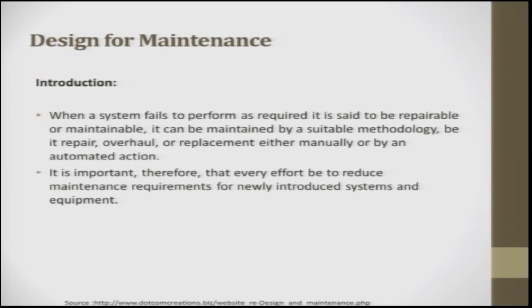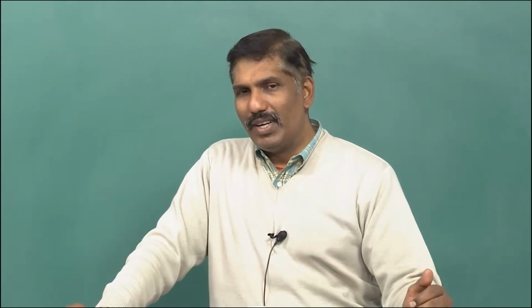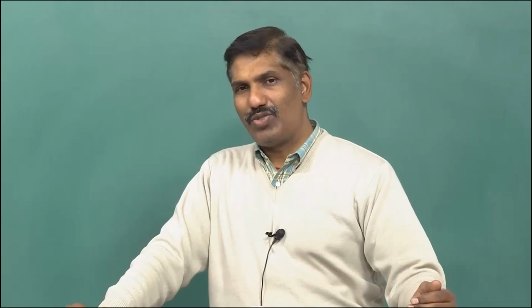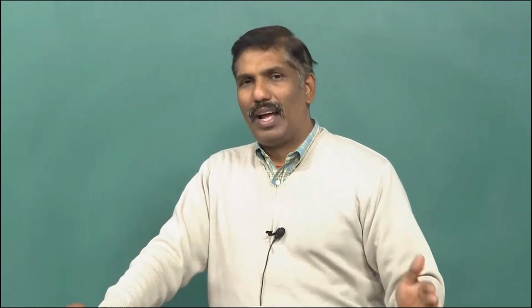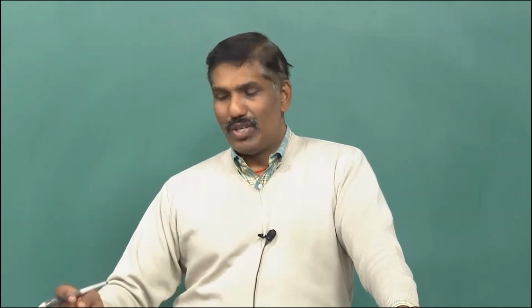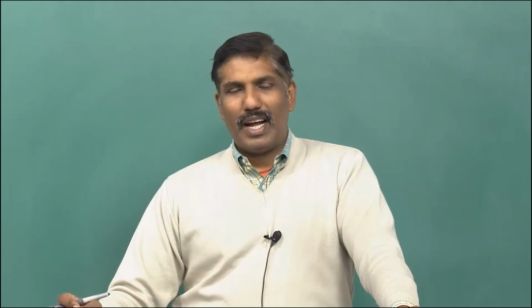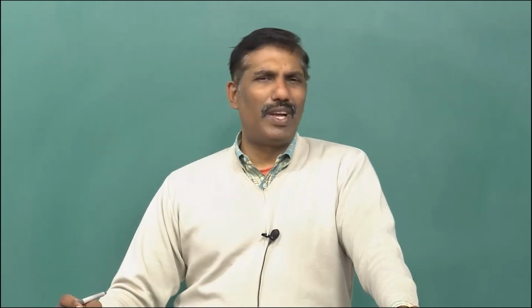It can be maintained by a suitable methodology, and maintenance also cannot be done haphazardly. So, today what is happening is we have preventive maintenance, predictive maintenance, and even the maintenance today, what they are saying is it has to be given a schedule and you have to follow that schedule, and in that schedule also it is not necessary that you should do 100% maintenance of all the parts. They try to divide, suppose if there are 100 spots where you have to look for maintenance, and in that also they try to rank them: which is more frequently to fail, which fails very rarely.